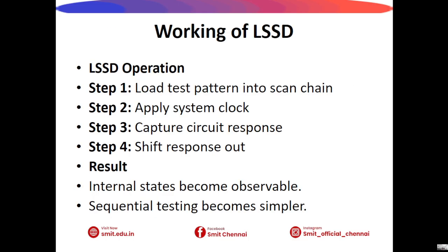Next we see about the working of LSSD. Operation of LSSD follows four basic steps. First, test data is shifted into the scan chain. Next, a system clock pulse is applied to capture the circuit response. Then, the response is stored in the latches. Finally, the captured response is shifted out and analyzed. This process provides excellent visibility of internal circuit states.